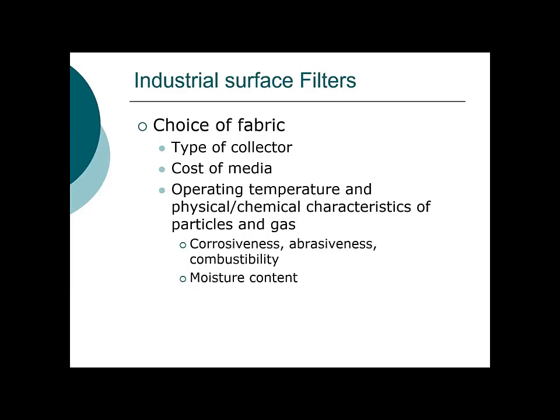And then the other issue has to do with the operating temperature. Again, as we just mentioned, there are some materials you cannot use at higher temperatures. The other issue is how corrosive is the gas? How abrasive is it? Are you dealing with a combustible gas? That will impact what you use. And also, what is the moisture content?